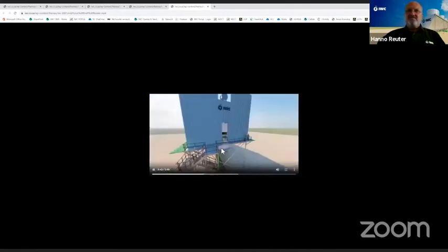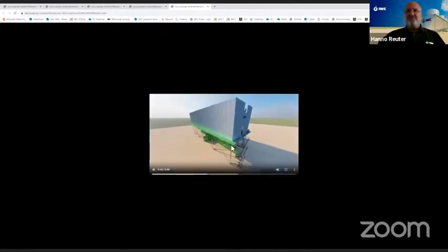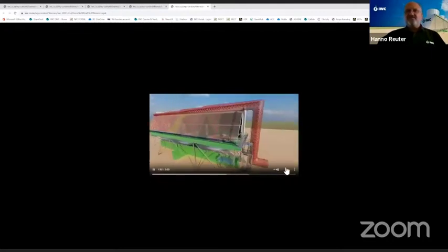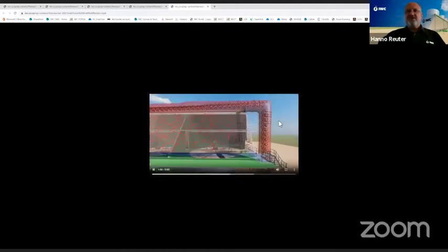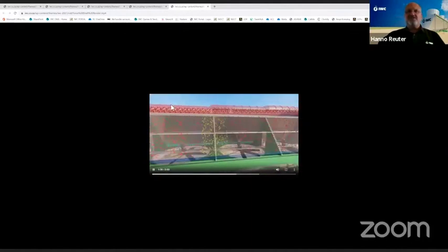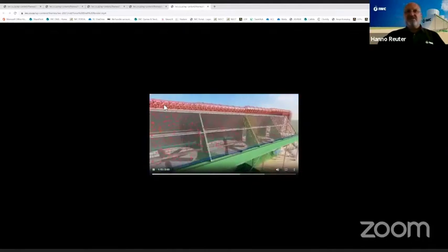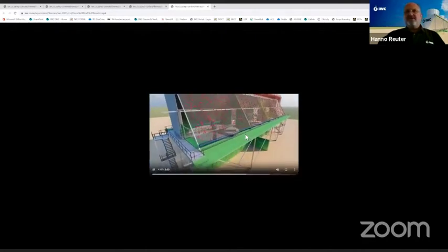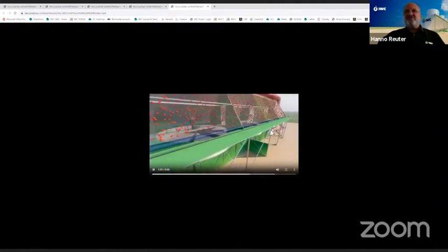Then you go outside, you see some special features, IWC features, which were developed at Stellenbosch University, this platform here and wind cross at the bottom. So how it works, the fans draw air from the environment and blow this air through these fin tube bundles. So you see the typical streamlines of the air. Inside the system, you have steam coming from a steam turbine, and it goes inside the main steam duct, and then is distributed inside these heat exchangers, where it condenses inside the bundles and leaves the bottom as liquid water, and that allows the pumps to repressurize it for the boiler.